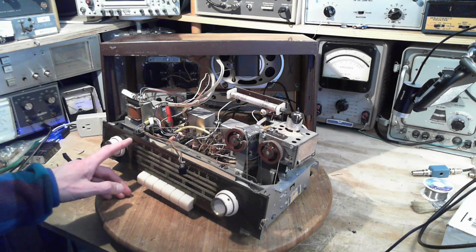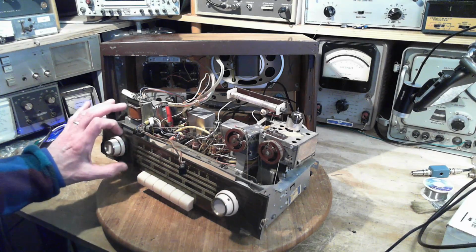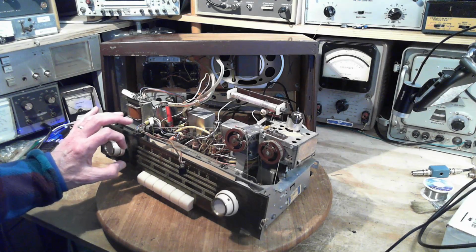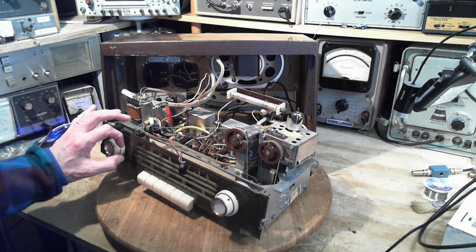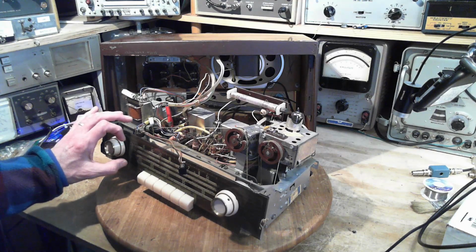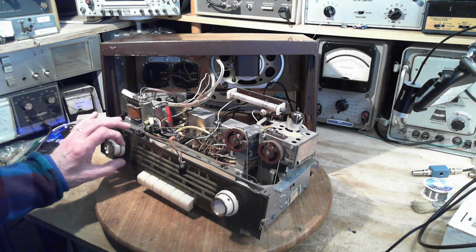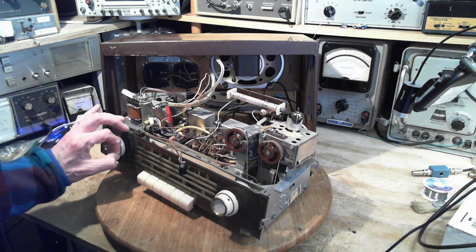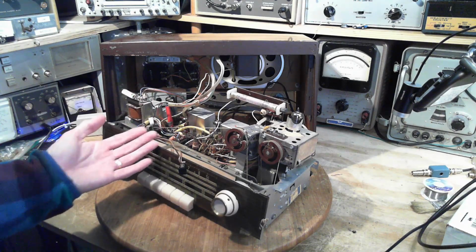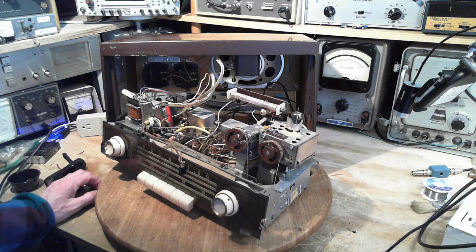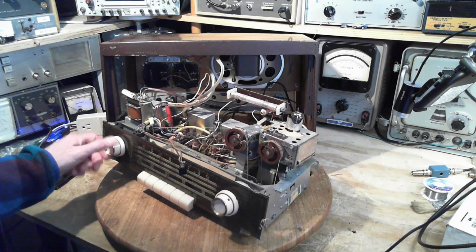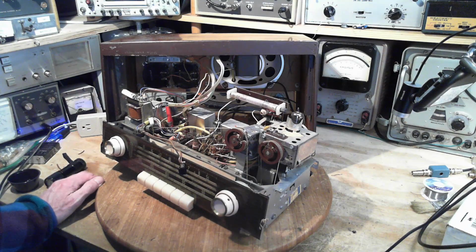So in some cases, the eye, which normally has two sharp bars on it, and then the bars just get closer and farther apart, always remaining very sharp. These bars stop being sharp and become fuzzy, very fuzzy bars. And they overlap, and they're closed most of the time. Meanwhile, the radio is screamingly loud. Of course, I can control that with the volume, but it is producing a lot of volume. In fact, I can't control it with the volume. When I have it turned right down, it's still producing sound.